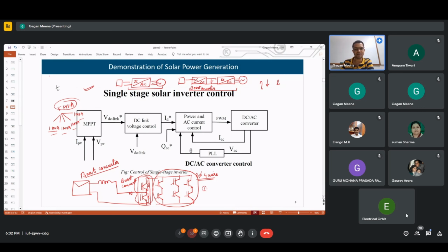For charging, because we do not want the voltage to go beyond a certain limit, as soon as it reaches 4.2 volts, the protection circuit will be activated and it will stop the charging. Similarly, the voltage should not fall below a certain value, which is 2.4 volts. Here also, as the voltage reaches this value, the protection IC will stop the discharging process.